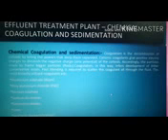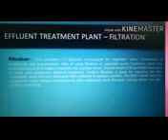And next, filtration. The utilization of filtration systems in wastewater treatment is a relatively late development. The idea of using filtration in wastewater treatment came into practice because of stringent requirements for reuse. The low levels of SS and BOD, biochemical oxygen demand, were hard to meet with conventional secondary treatment.